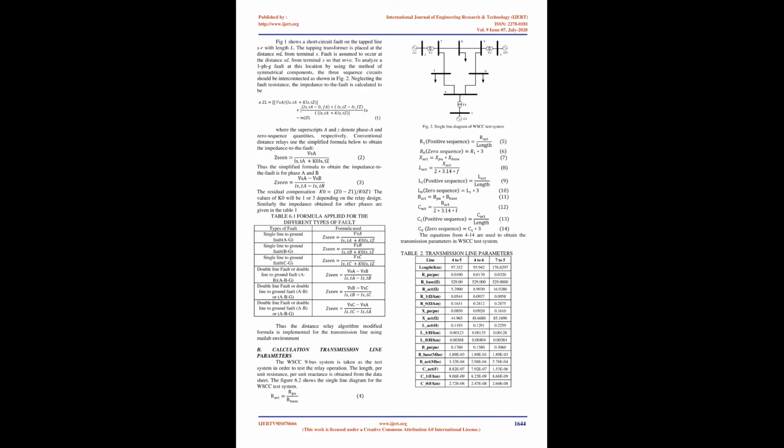Some electromechanical relays also use electrothermic principle of operation, based on the forces created by expansion of metals caused by temperature rise due to flow of current. Such relays are called thermal relays. It is not practical to make a relay that develops a torque equal to the quotient of two AC quantities. The only significant condition for a relay is its setting, and the setting can be made to correspond to a ratio regardless of the component values over a wide range.